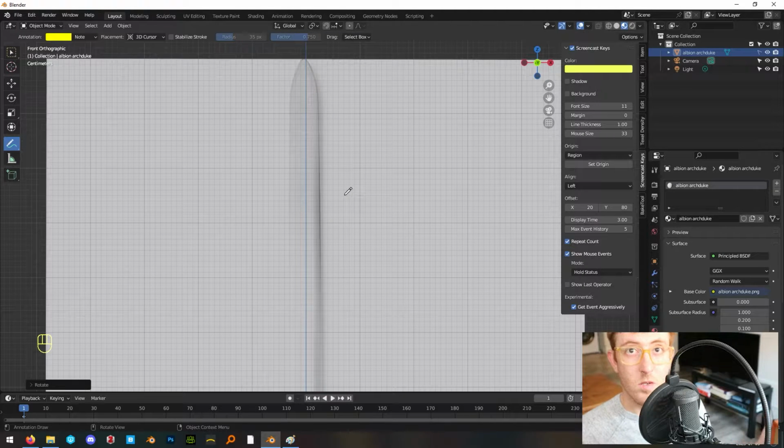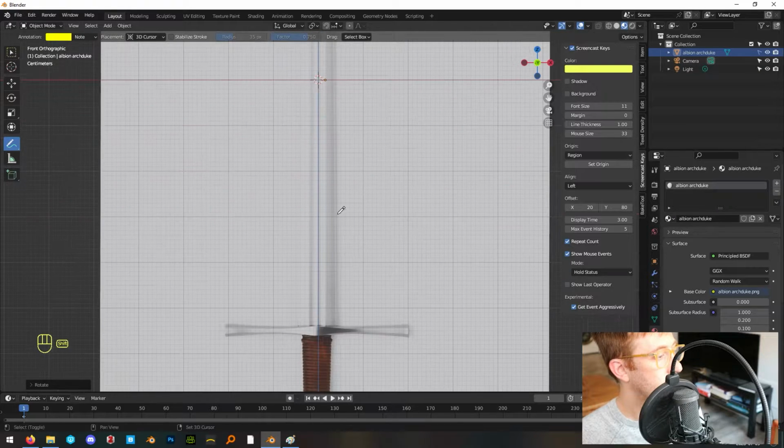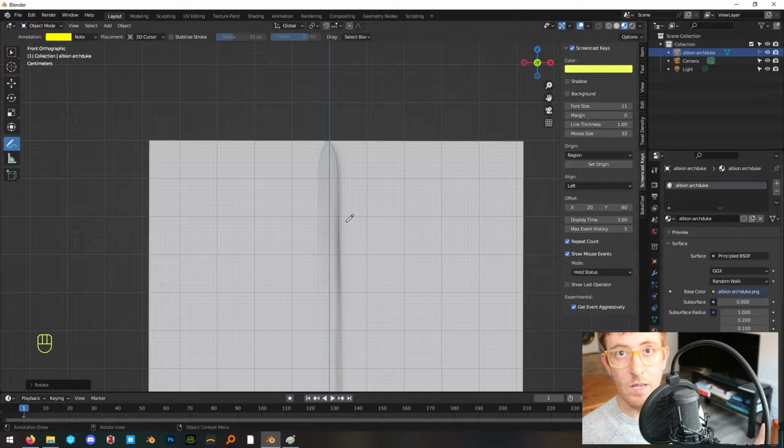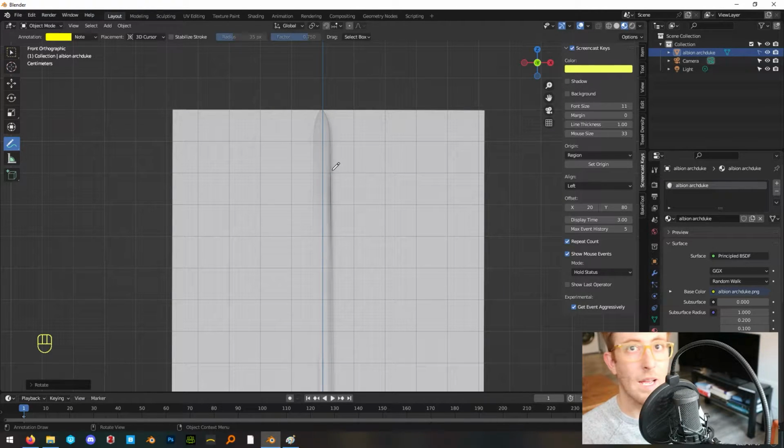The sword is actually a little bit tricky to model, and the reason is because of this groove in the middle. We want to have that depressed, but we don't want it to cause any weird shading effects. We haven't really talked about edge flow yet, but in order to get this the way that we want, we would like to be able to add a loop cut around that so that it can have a sharp edge when we subdivide the blade.